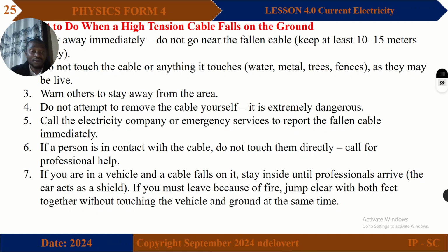One, stay away from the area. Do not attempt to remove the cable yourself. Call the electricity company's emergency service to report the falling cable immediately. If a person is in contact with the cable, do not touch them directly. Call for professional help. If you are in a vehicle and a cable falls on it, stay inside until professionals arrive. The car acts as a shield.